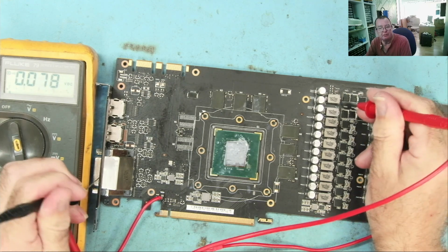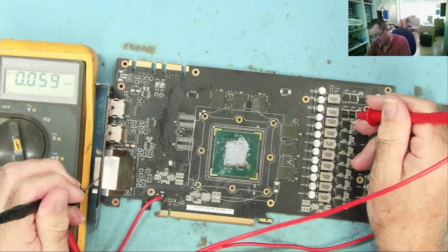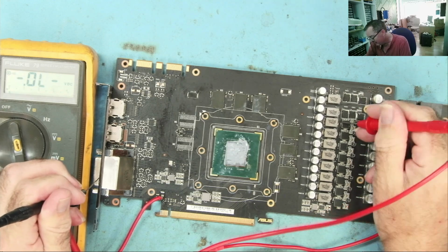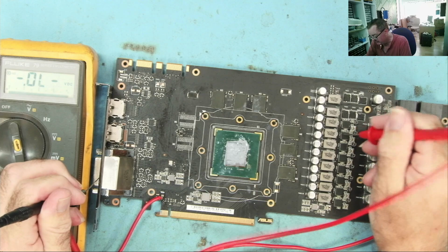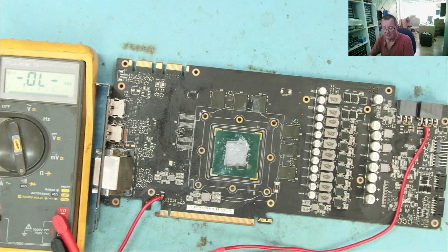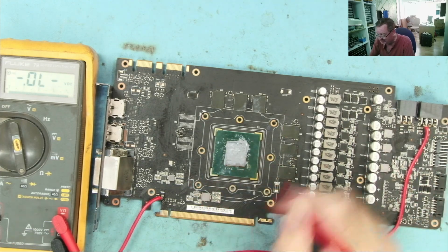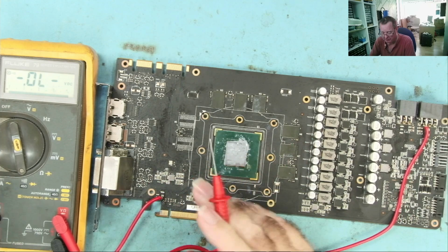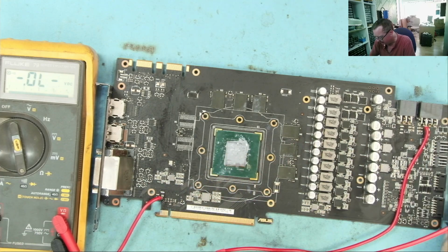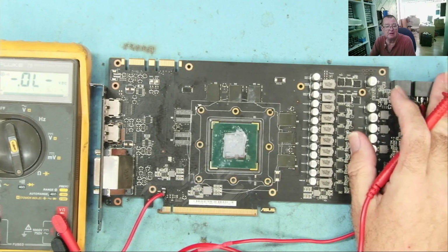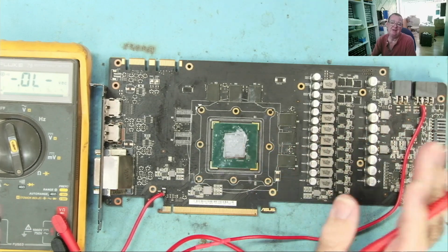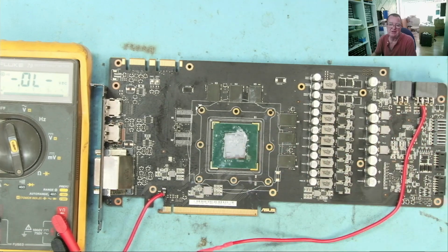You think you've got a short, yeah? Or it is there. These are just reading short. So you can see that in this situation, use resistance mode. You'll just make life difficult for yourself if you do it in diode mode. Eventually you'll learn, but I've told you now, yeah, you know what to use.